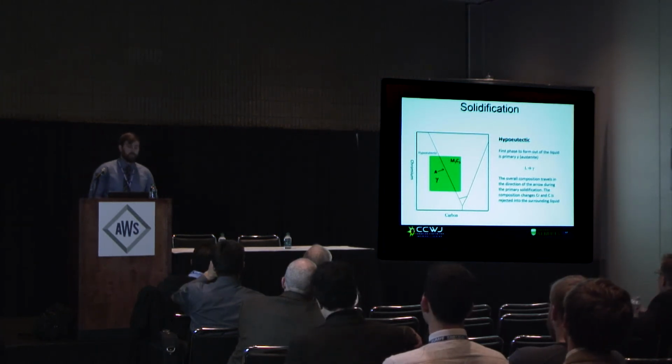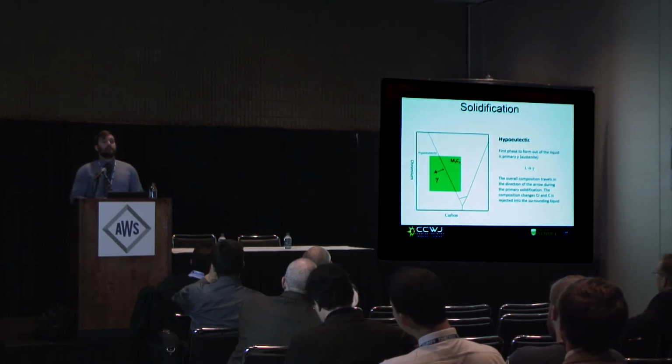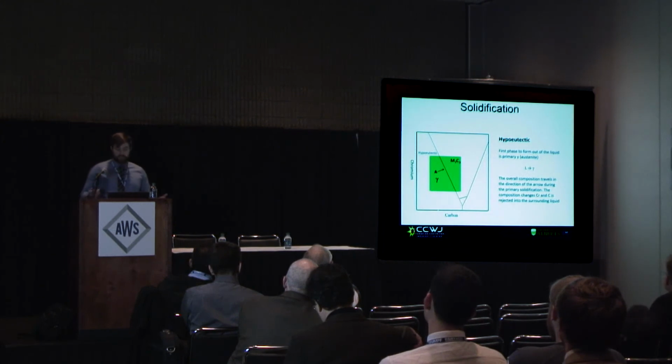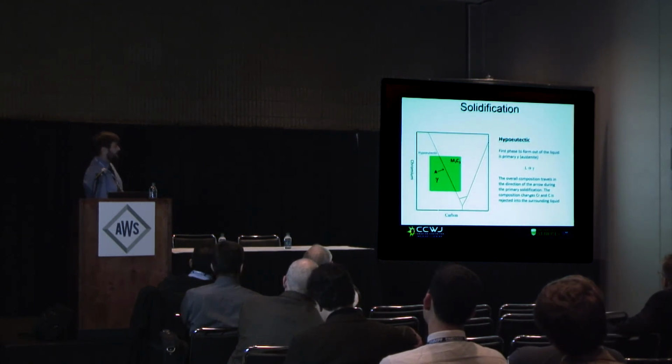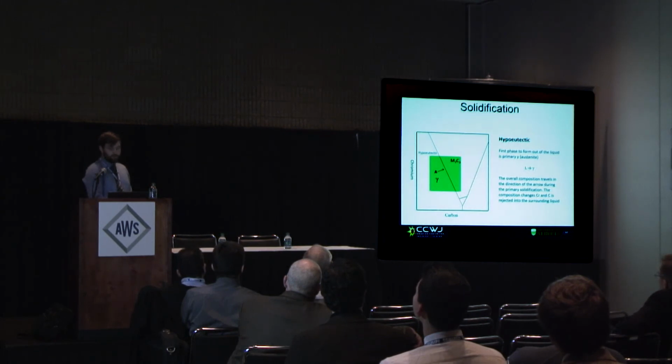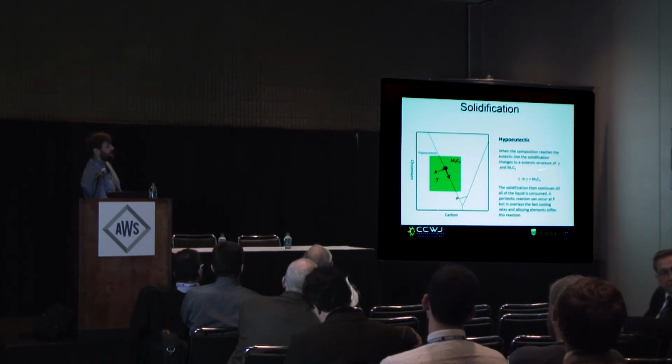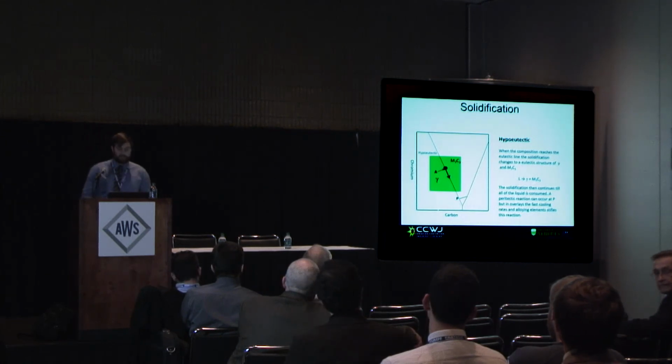austenite. As the austenite is coming out of liquid solution, the composition is changing towards this line because chrome and carbon is being depleted. When it reaches this line, you then get a eutectic structure come out of austenite and M7C3.